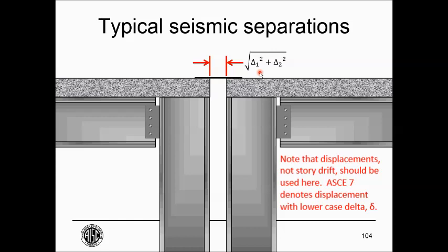Now, it could be that the joint cover is damaged at that level of displacement. That's not a structural safety requirement. That's simply a question of what is acceptable to the owner and essentially to the industry. And generally the industry has designed these joints to have some level of damage under these very large levels of displacements, that is to say the C sub d level displacements.